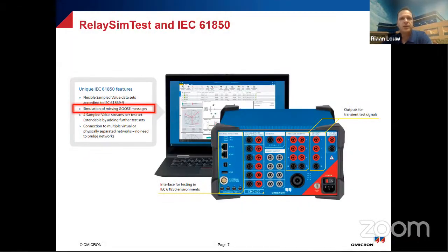Okay, coming now to our next slide, RelaySimTest and IEC 61850. Leaning a bit more into our presentation for today, our practical session, the full IEC 61850 support in RelaySimTest allows users to import the substation architecture or configuration. So this would be your typical SCL or SCD, or your ICD, CID configuration files and so on, into RelaySimTest so that it becomes part of your test system.